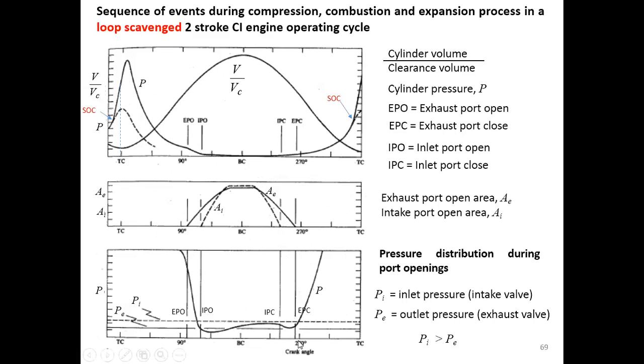Okay, and then the pressure keeps going up because the piston moves up to the top dead center and both ports are closed. We have a closed volume. So this is how the gas exchange process happens. It depends on the outlet pressure and on the inlet pressure of the fuel that is injected into the cylinders, and it shows you right here on this third diagram.